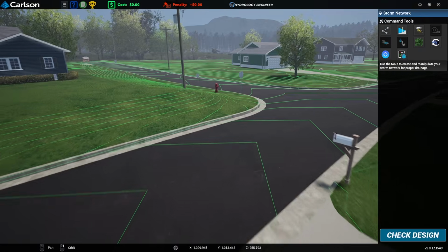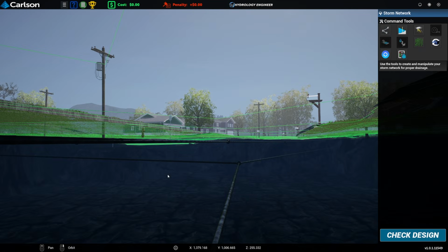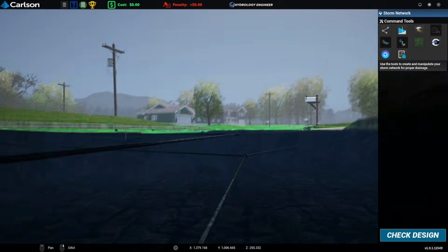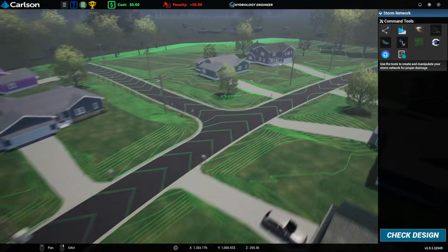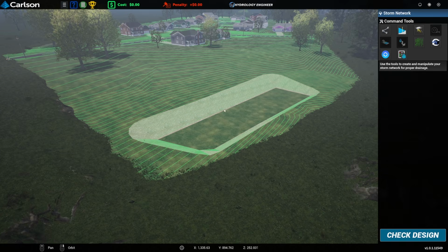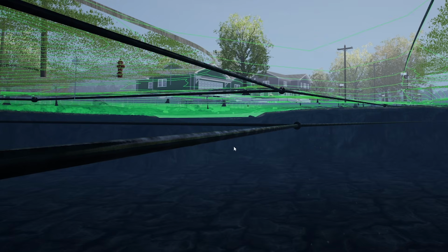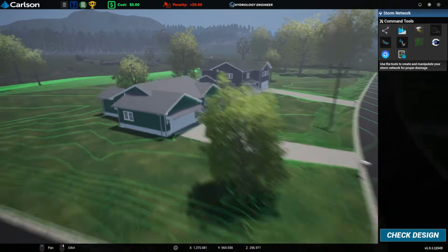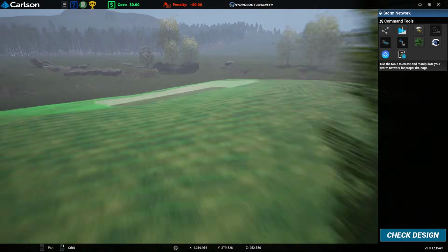But yeah, so that ends up somewhere else because we're worried about the surface water drainage, the drainage from the rain in the sky. And so when you look at these, you want to make sure that your pipes are always above these wastewater pipes, because if you remember, our surface water generally ends up over in a pond where it evaporates or soaks into the ground. And so if our pipes were below the foul sewer, and this sewer then leaked, all that poo water, the horrible sewage, would leak into our drainage system, and then that would end up over in our pond, which obviously wouldn't be very nice.